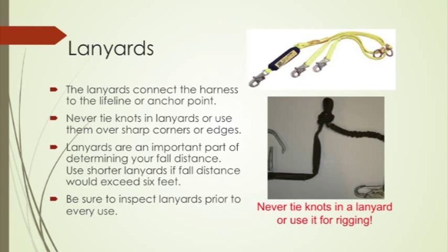Most of the time, the shock-absorbing part of a fall arrest system is on the lanyard. You should avoid having lanyards on site without shock absorbers, because they can be easily confused and used for fall arrest. Lanyards without shock absorbers should only be used for positioning.